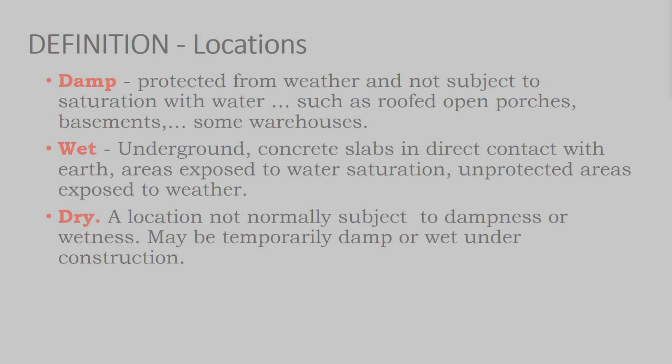The danger is during construction, if the array is not fully complete, you might have loose connectors and wiring hanging off all of these components. And I have seen damaged electronics where the install crew might mount the optimizers or microinverters at the end of the day, and then they don't plug them up and it rains overnight. Water gets into the connector.